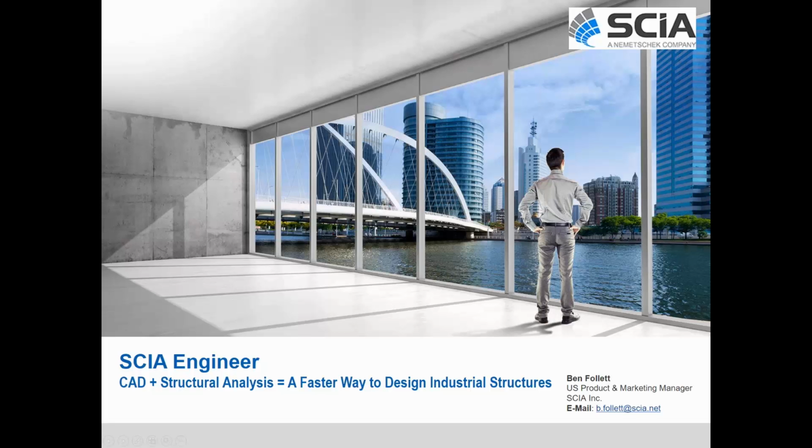The first is a question relating to using truss properties for braces in SCIA Engineer. I'm not 100% sure exactly what you're asking, because you're referring also to STAAD, but you can set an element to be a truss element. You could set elements to be truss chords and to have interaction, so maybe they would be axial only, so they're not going to take any bending or whatever. And so that is certainly possible. That's just an option to select. When you select an element in the properties, it would say axial only. Obviously, as a nonlinear type, you can always set it to tension only or compression only, and so forth.